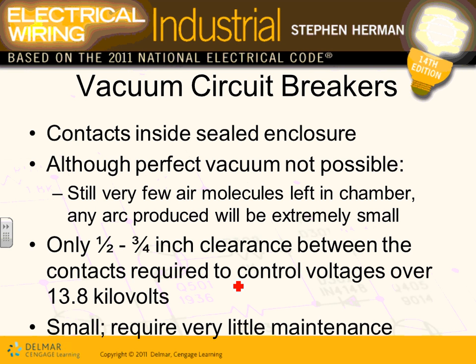The key point about a circuit breaker, guys: if you interrupt the short circuit, do you want to reset them and move on? Or do you want to replace them? If you want to replace them, might as well put a fuse, right? Fuse, open, replace it. That's why when it comes to circuit breakers, it's a big deal. They need to live to fight another day after they interrupt.